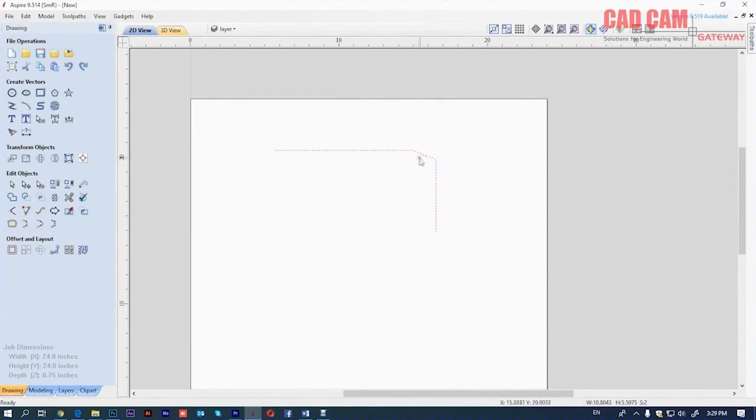together with a 3rd line. Here I selected all 3 objects and used the join command. When I closed the join, I selected these 2 objects and connected them together here. Then I selected these 2 objects and joined them together, and then I selected these 2 and joined them as well. So one by one. If you keep selecting 2 objects at a time, it will keep joining them together. I'll undo this.